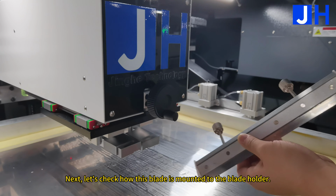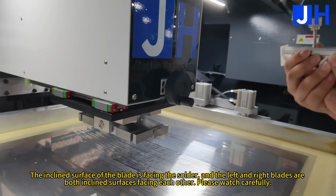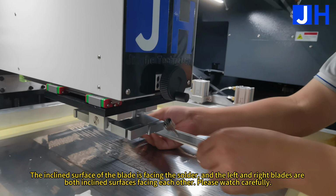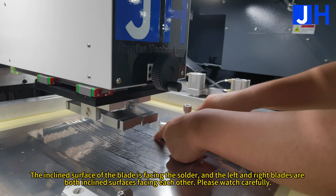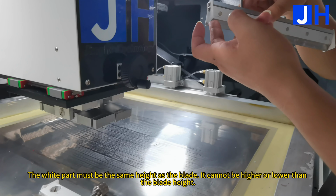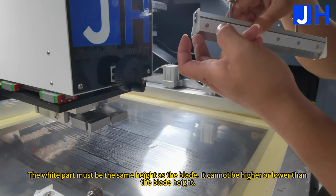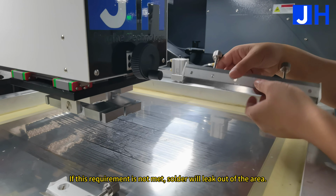Next, let's check how this blade is mounted to the blade holder. The inclined surface of the blade is facing the solder, and the left and right blades are both inclined surfaces facing each other. Please watch carefully. The white part must be the same height as the blade. It cannot be higher or lower than the blade height. If this requirement is not met, solder will leak out of the area.